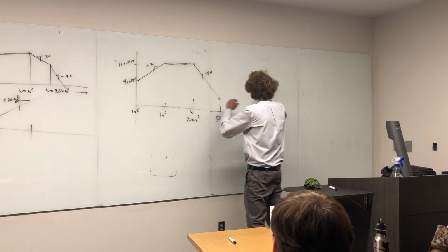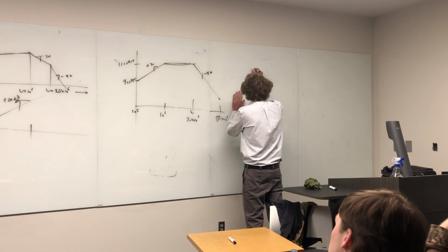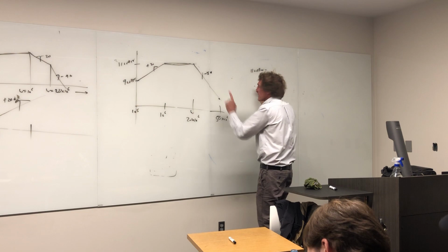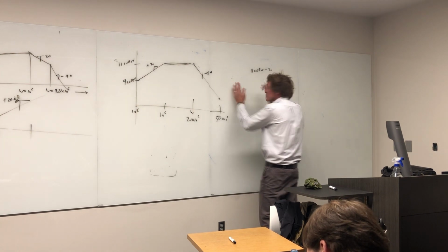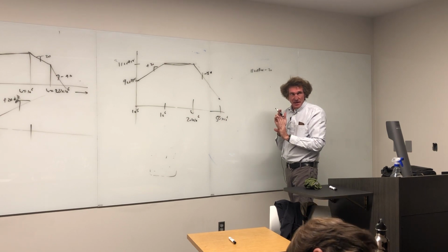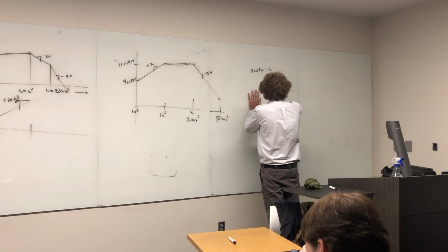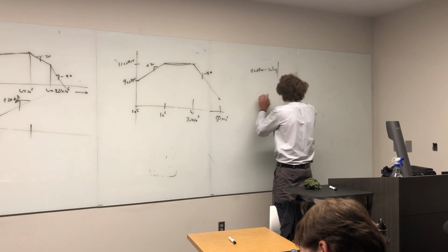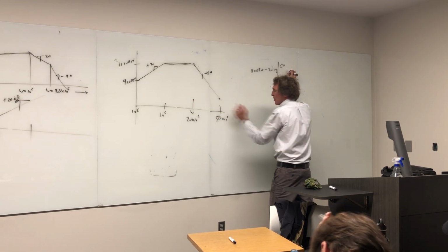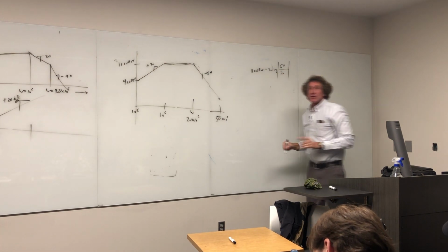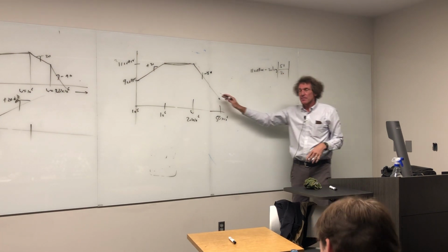So here it's going to be 110, right? And that's dB microvolts. Then you take minus 20. That's the rate that it falls, right, per decade. Got it? And then you're going to take the log of the frequency you end up at, which is 50 megahertz, over the frequency you started at, which is 20. And now you're going to have that value right here.